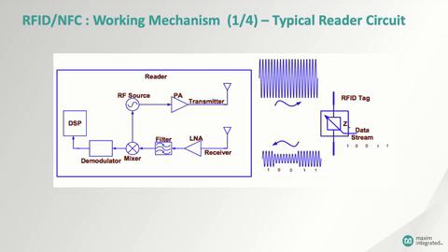Okay, now in the tag, there's frequently a memory device, an EEPROM if the data needs to be changed from time to time, or a ROM if the data is fixed. The memory is generally pretty small, a few kilobytes at most, and it might contain an identifier, a bit of program code, temperature records, fabrication records, location information. Hey, really, it could be anything.